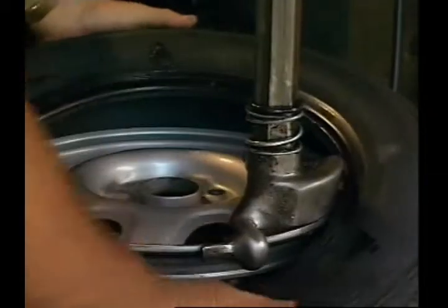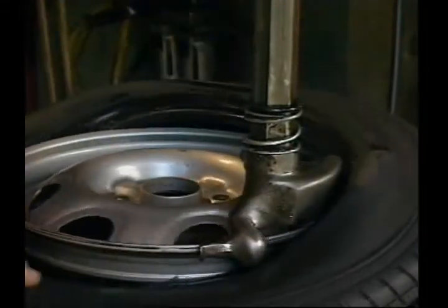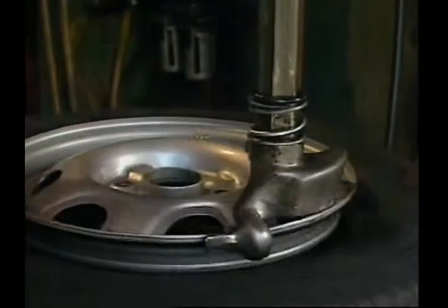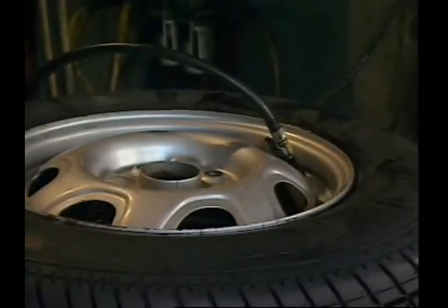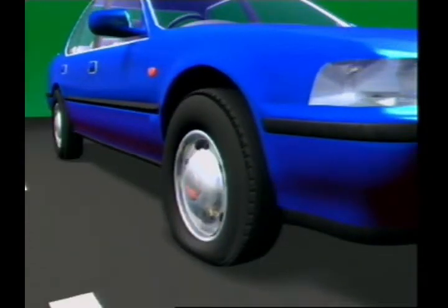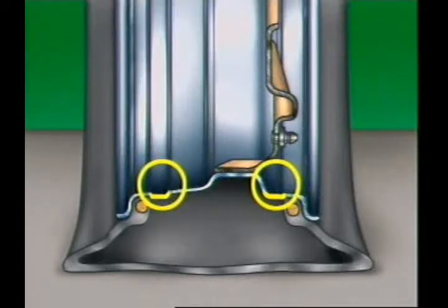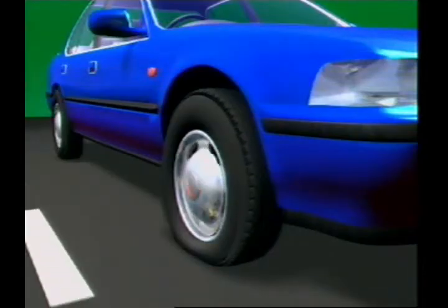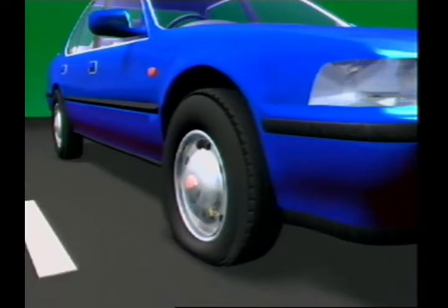Passenger cars normally use rims which are of well-based or drop-center design. The drop center is used for mounting and demounting the tire onto the rim. When inflated, the tire is locked to the rim by tapering the bead seat towards the flange, or by safety ridges or humps close to the flange. In the event of sudden deflation or blowout, safety ridges prevent the tire moving down into the well. This helps maintain control of the vehicle while it is being braked.